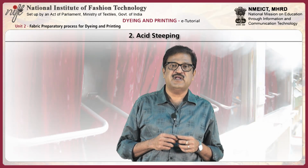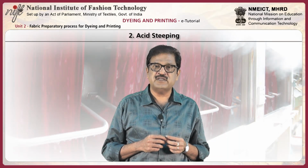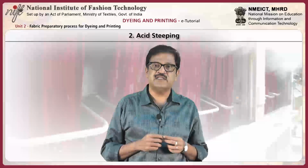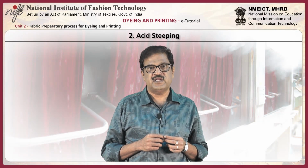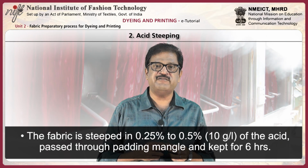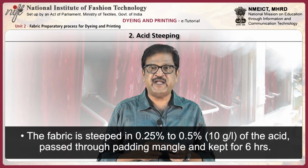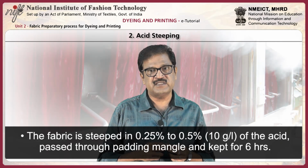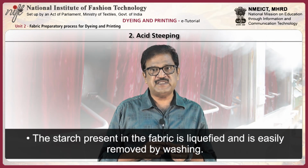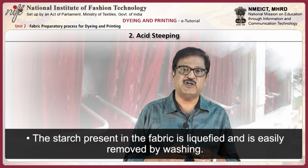Acid steeping. In the acid steeping method, dilute hydrochloric acid or sulfuric acid or a mixture of both are used to hydrolyze the starch from the sized fabric. The fabric is steeped in 0.25 to 0.5 or 10 grams per liter of the acid, passed through a padding mangle and kept for 6 hours. The temperature rises to 50 degrees Celsius. The starch present in the fabric is liquefied and is easily removed by washing.